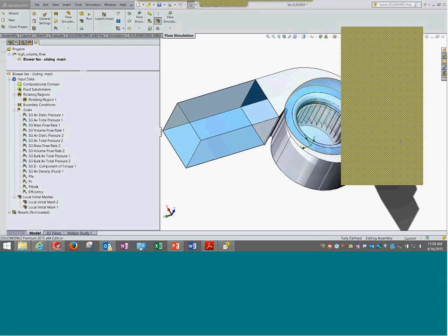Can we see the sliding mesh moving, for instance by plotting the mesh at different time intervals? Can the sliding mesh be used to simulate moving objects other than a rotating region? So definitely it cannot be used for any other object apart from a rotating region. Okay, that is for sure. And in terms of moving, as I showed you in yesterday's animation, we can actually see these things.